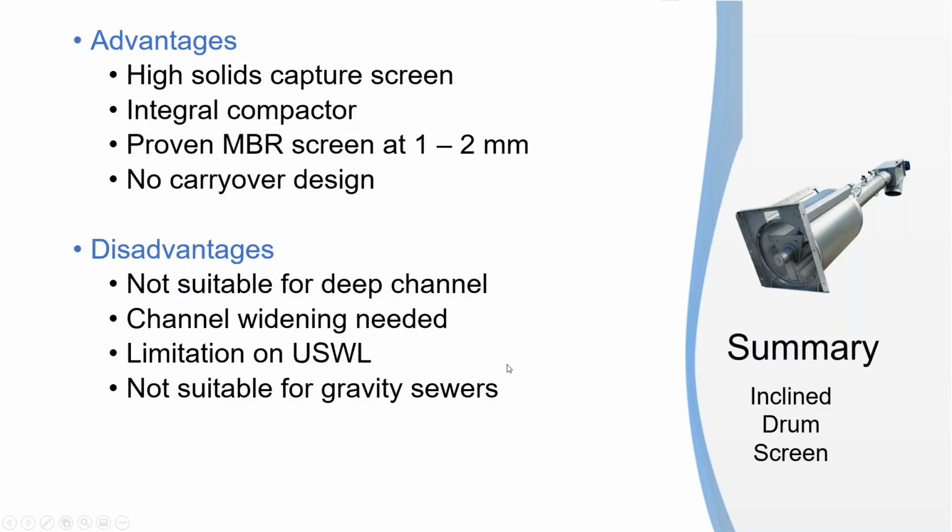It's also not great for gravity sewers because while it can typically handle some debris getting in, it can't handle conveying them up and out due to the auger size.